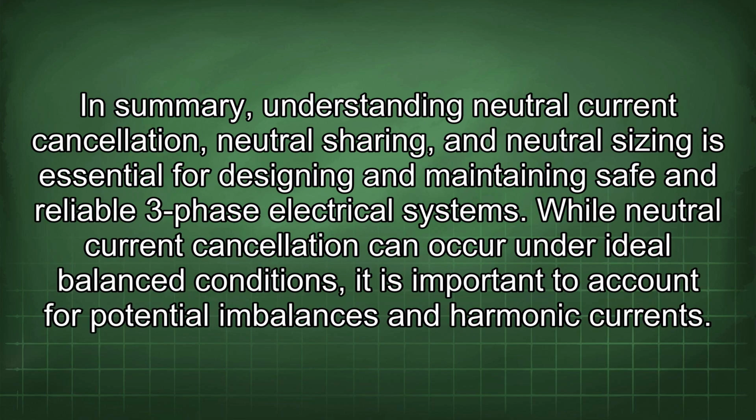In summary, understanding neutral current cancellation, neutral sharing, and neutral sizing is essential for designing and maintaining safe and reliable three-phase electrical systems. While neutral current cancellation can occur under ideal balanced conditions, it is important to account for potential imbalances in harmonic currents.